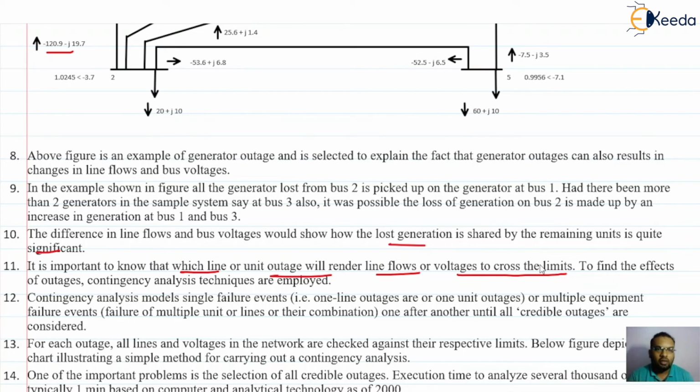After that, let's say from the contingency definition and selection we get that the first contingency is the failure of the line between bus 2 and 4, the second between bus 2 and 5, then generator failure. Then we can check the severity, which line failure or which generator failure is more severe, and accordingly we now have the list.